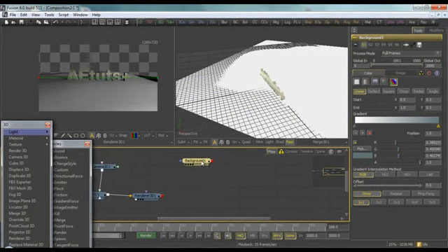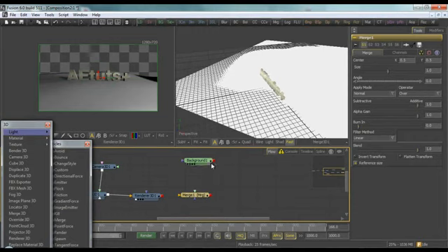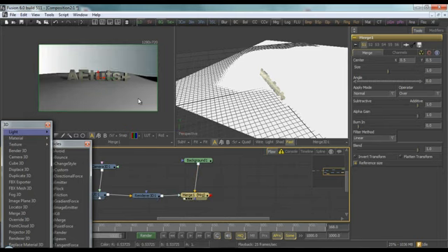And we have to merge the render 3D and the background together. We can do it by pressing merge and drop it into work area. If you're not sure which input is the right one, you can just hover above it and it will tell you what is background and what is foreground. As you can see, the yellow is always the background. So connect the background to the background node input, and select renderer, foreground, and just throw this tool into renderer, and we have something.